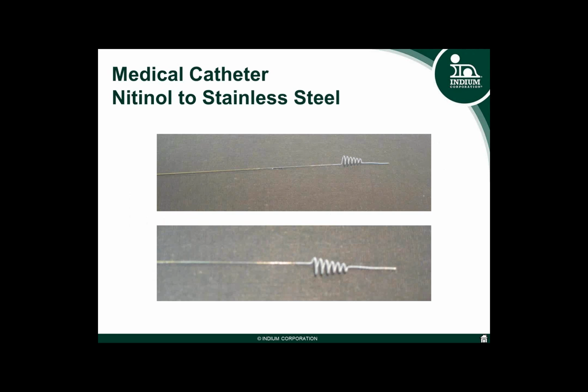These alloys are joining here, especially to the stainless steel, which has different levels of oxidation or harder oxides on the surface. So these will require slightly different fluxes that are used in the PCBA. These fluxes will be stronger, more acid-based, and will need some sort of cleaning afterwards to remove them from the application.